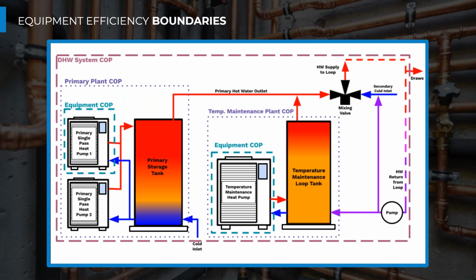So when it's 100 degrees outside, the person in that apartment unit is operating their cooling, which means they're discharging heat from that outdoor unit into whatever space it's in. If it's in the garage, we're discharging heat into that garage, and that's heating up the garage. With more of these split system heat pumps going into buildings, we're seeing that garage air temperature is actually increasing during those cooling periods.